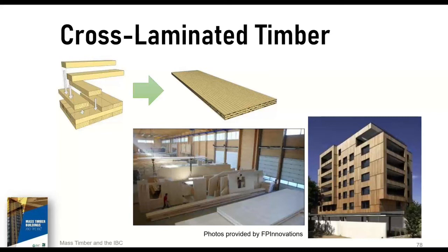Each billet of solid wood can be from 4 to 18 inches in thickness and up to 11 feet in width and up to 65 feet in length. Exact sizes will vary by manufacturer and project. The resulting panel of wood is dimensionally stable in plane because there is parallel-to-grain lumber resisting shrinkage in both panel directions.